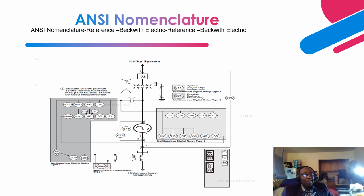Next is 64F, and this is basically the rotor field ground relay that detects faults on the rotor winding. If there's a short on the rotor or field winding failure, this relay is the one that detects it and trips. And I made mention about high impedance grounding, right?